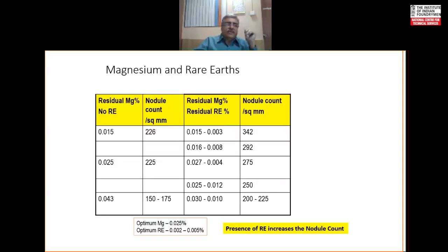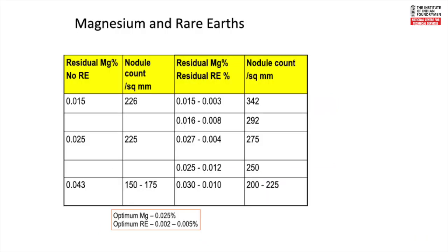Here is a table which shows the effect of rare earths on nodularization. Instead of going through the table, I'll only say that the presence of rare earths increases the nodule count, as you can see from this data from an experiment done in the labs.